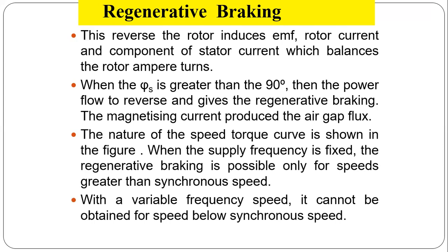When phi S, the phase angle, is greater than 90 degrees, the power flow reverses and gives regenerative braking. So if the phase angle is less than 90 degrees, it works as a motor, and if the phase angle is greater than 90 degrees, it works as a brake. In that case, we are using it as regenerative braking.